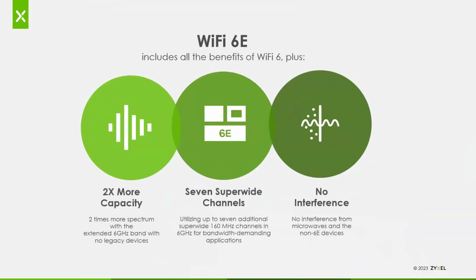So I do want to talk a little bit about Wi-Fi 6E. I've told you which models have it. Short version is Wi-Fi 6E is just Wi-Fi 6, but it's been extended to support 6 gigahertz. So traditionally, Wi-Fi has operated at 2.4 and 5 gigahertz. A couple years back, the FCC and governments around the world opened up a big chunk of the 6 gigahertz spectrum. So it's a new spectrum. It's a higher frequency. It's a much larger area that we can use.